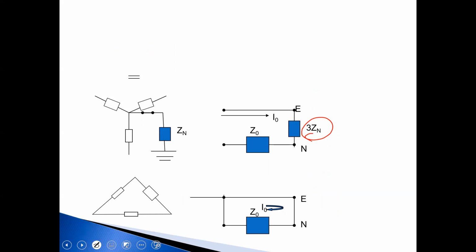Okay? And this is, well, I shouldn't say this, but one of the benefits, you will explore this in your fault analysis lab. You will look at the benefit of having a star delta transformer. Why do we connect them? Really and truly, simply put, it's just to separate or prevent zero sequence currents from moving from one point of the network to the next.